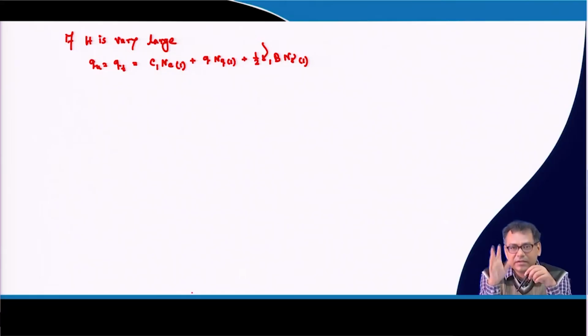You will get maximum bearing capacity if all the influence zones of the foundation are within the first layer or within the H. This is only possible if H is very large. So, that is the limiting value, your bearing capacity cannot be greater than that value. Because the lower layer is the softer or weaker layer, as more influence zone is covered within the lower layer, your bearing capacity will decrease. So, that is why a limit is placed.